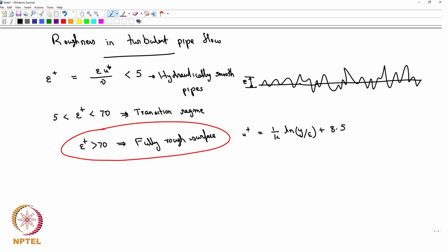I'm not sure whether you can really characterize that structure, because the graph that we drew was for strictly smooth pipes. Now we are borrowing some of those ideas to talk about roughness. So in principle, some of those numbers might change. That must be what is happening in reality. But if you strictly borrow it, then we are really into the overlapping.